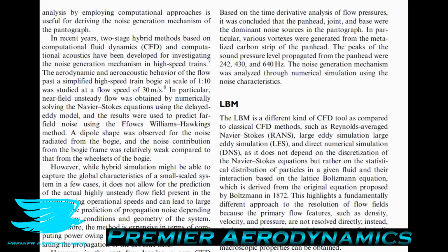So one thing we should talk about is that traditional CFD, so using Navier-Stokes equations, particularly URANS and even DES and even LES to some extent, they're not very good at predicting the aeroacoustic behavior of objects.